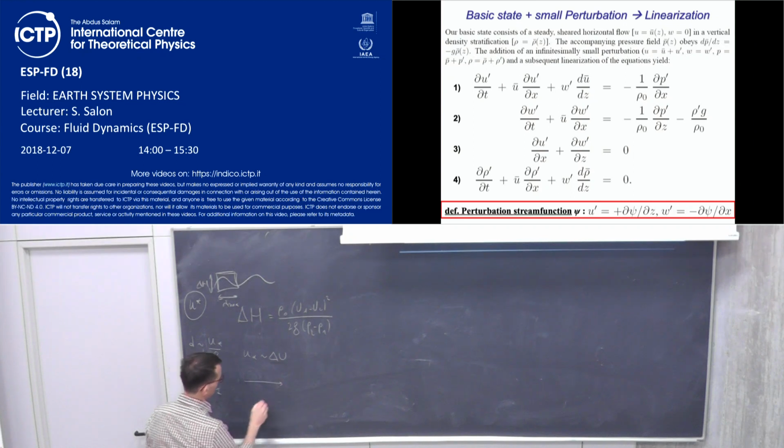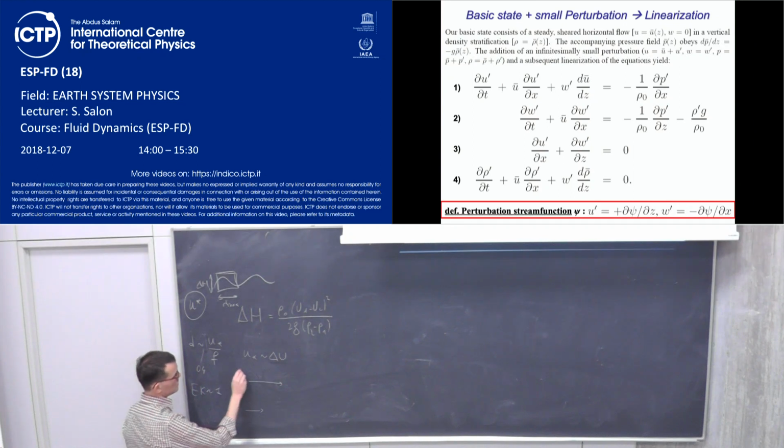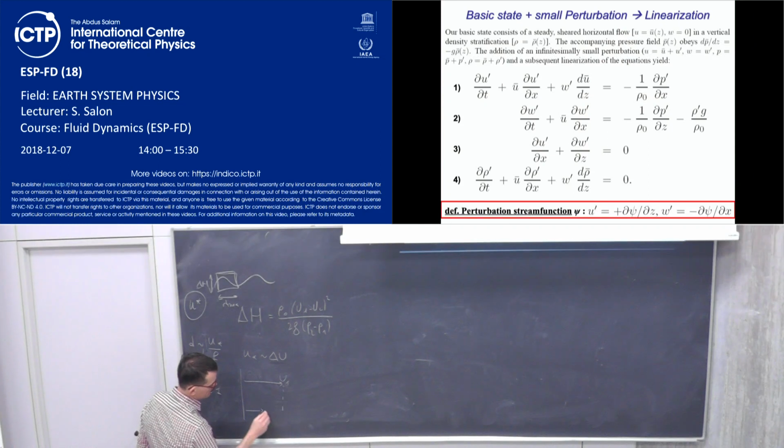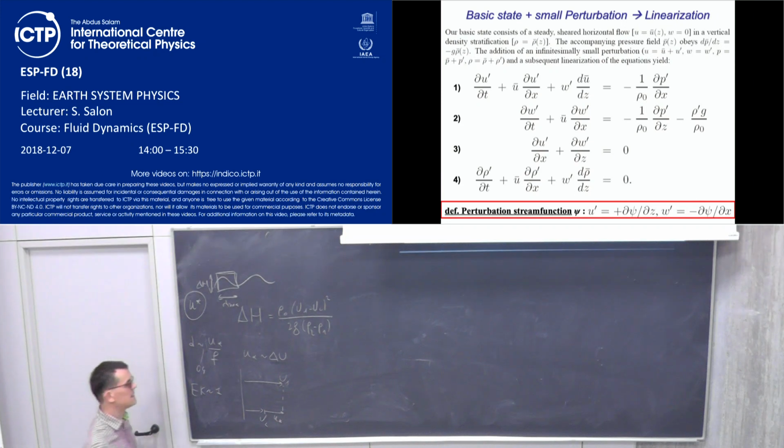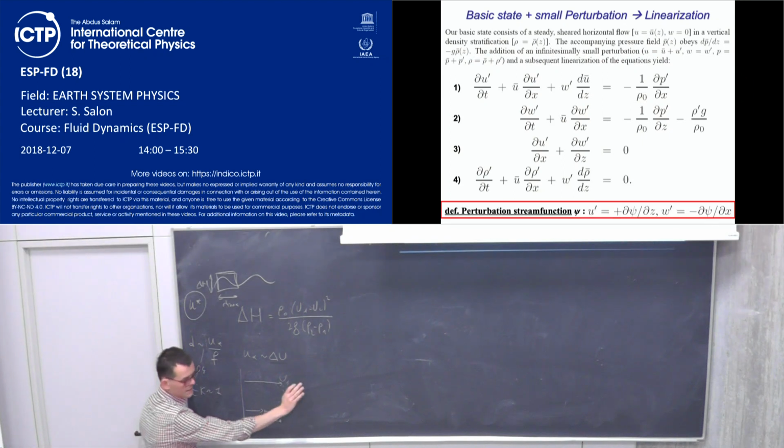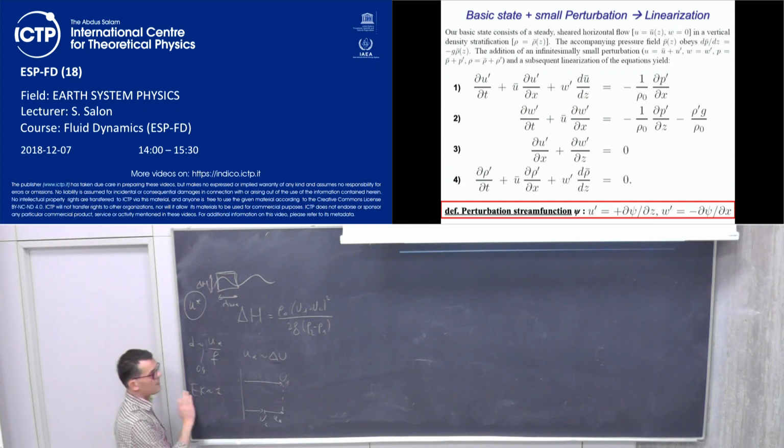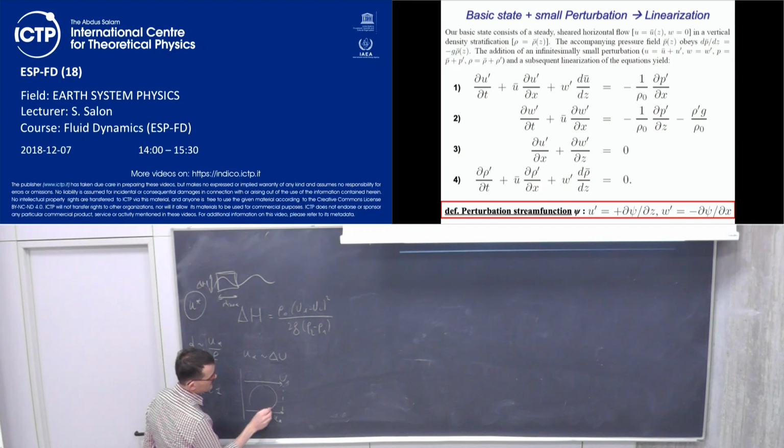So if I have, let's say, a shear like this, U1, U2, the difference between the two, I can represent it as the friction velocity. Intuitively, you can say that if you have a fluid like this, looking from above in the river, that we talked about a couple of lessons ago, there is a flow faster here, slower here, and what you have is something like this.